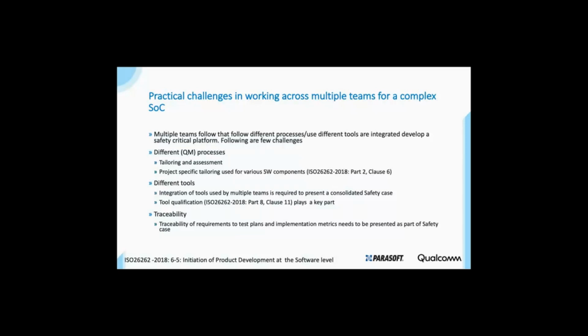We have to go through a detailed tool qualification, which is ISO 26262 Part 8, Clause 11. So we first do the tool classification to see what TCL level they fall in. And then we have a Qualcomm defined tool qualification process with the help of our quality team, and we finally produce a detailed qualification report.